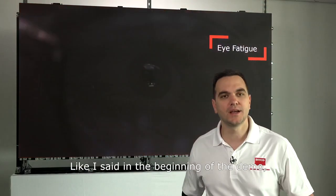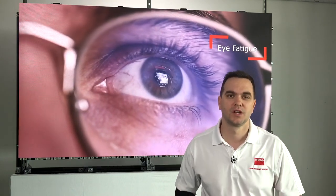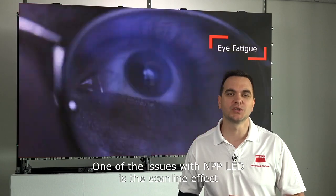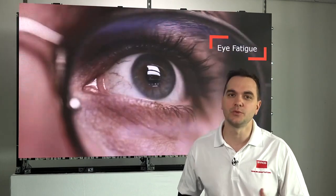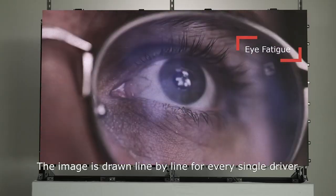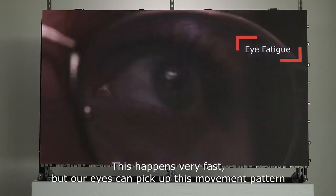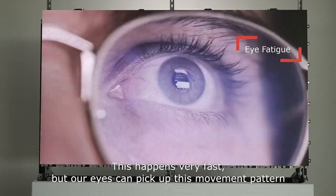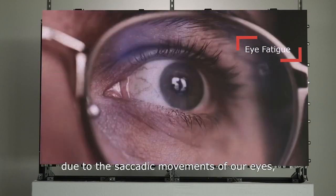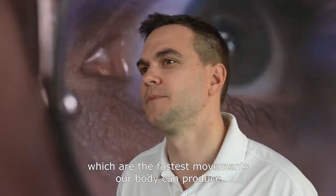Like I said in the beginning of the demo, TruePix is the ultimate control room overview wall. One of the issues with narrow pixel pitch LED is the scanline effect, which can be perceived as visual flicker. The image is drawn line by line for every single driver. This happens very fast, but our eyes can pick up this movement pattern due to saccadic movements of our eyes, which are the fastest movements our body can produce.